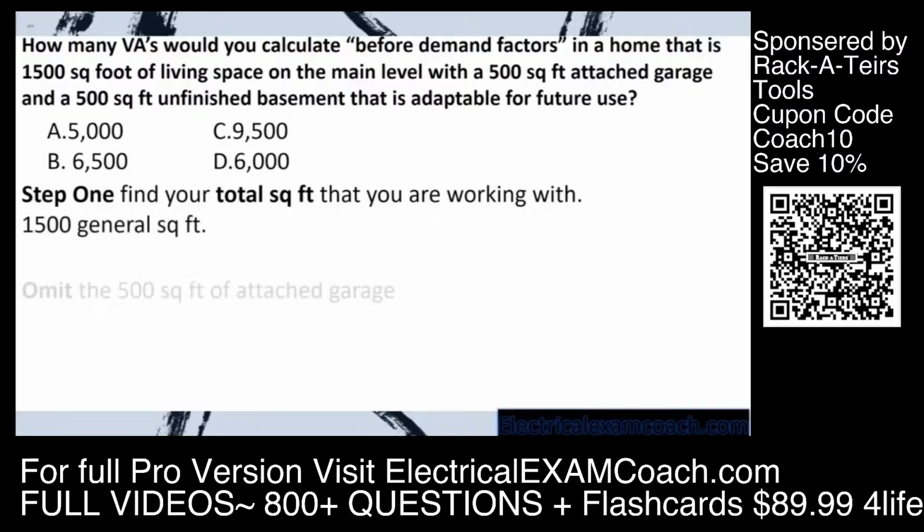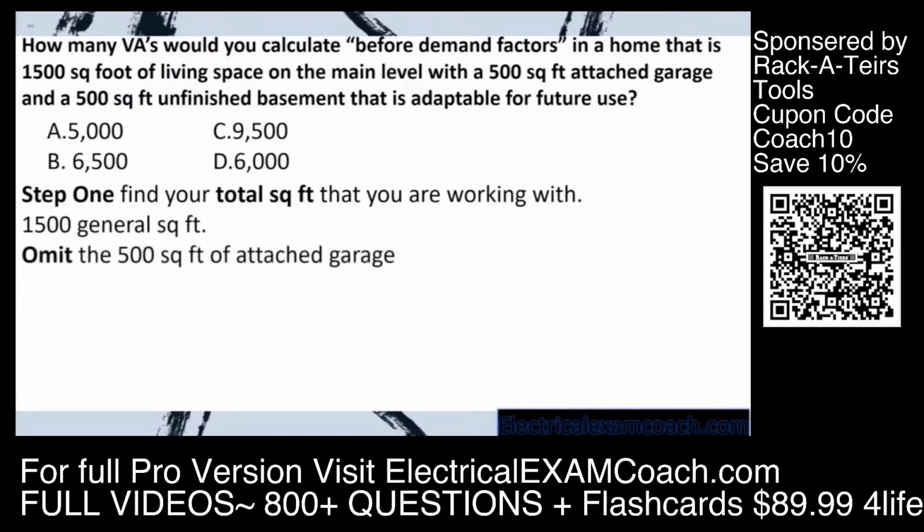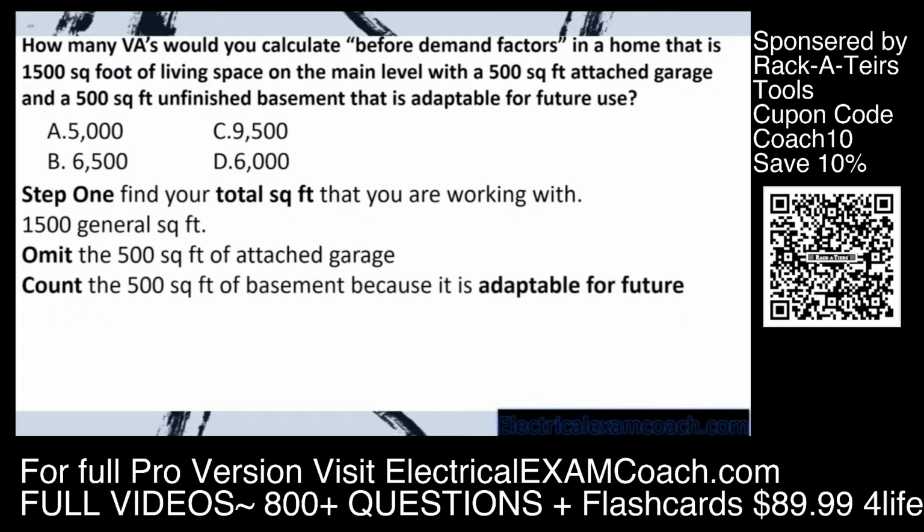We will count it. Then we're going to omit the 500 square foot of attached garage. We're going to count the 500 square foot of basement because in this question, it is adaptable for future use. In your testing, it'll say either or, and in the real world, it's almost always adaptable for future use, but you can work that out with your local electrical inspector.